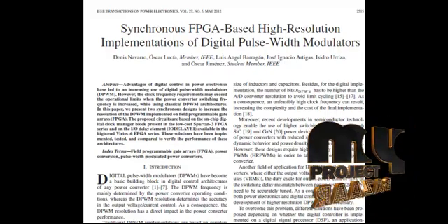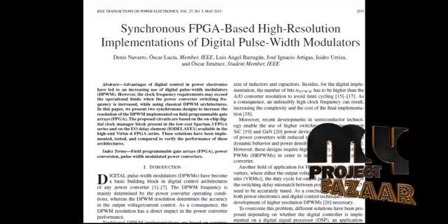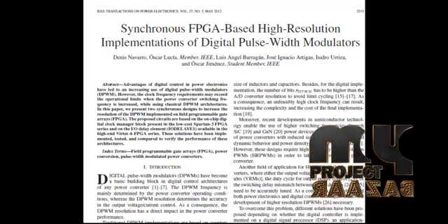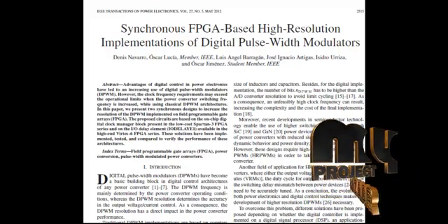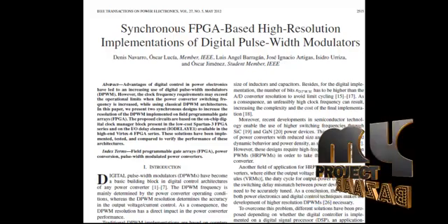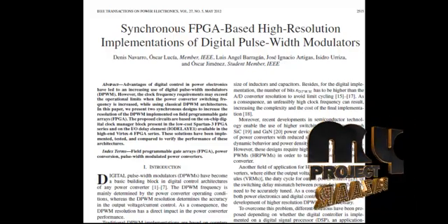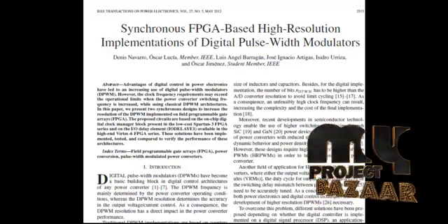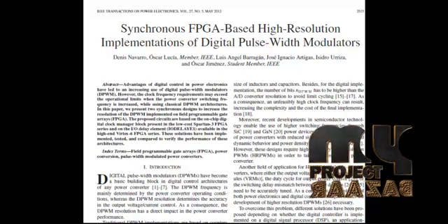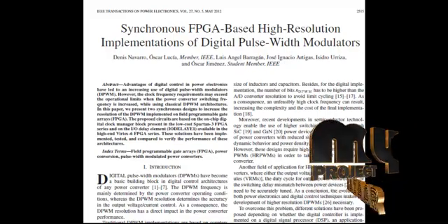For digital pulse width modulation, a lot of different architectures have been proposed in recent years, and even a classification of them has appeared. Although all these architectures differ from each other, almost all of them make use of delay lines. The advantages of delay line DPWMs are high resolution and low power consumption. However, they have lower linearity and non-monotonic behavior in some cases.